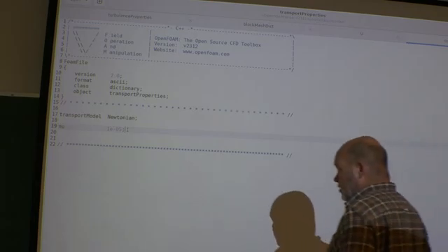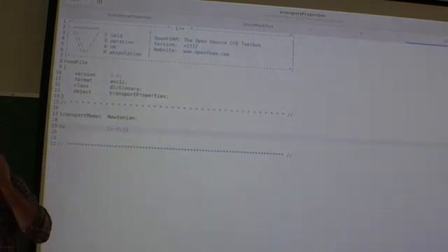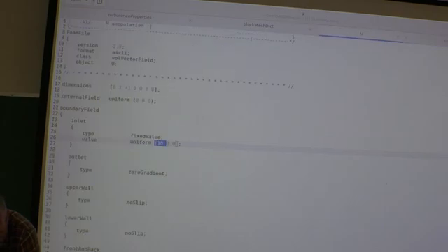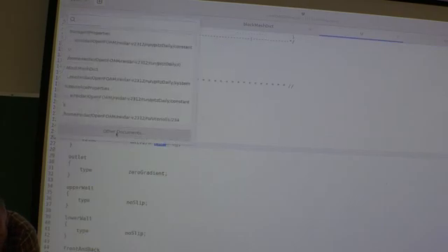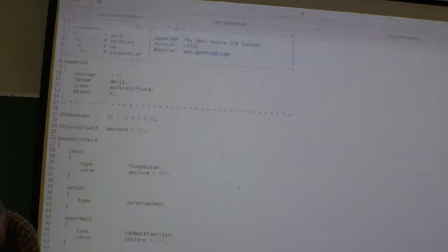So yeah, it's highly turbulent, clearly. If you want to change the Reynolds number, I would suggest you change the viscosity. That's the easy way, instead of having to create new meshes, everything. Okay, then let's have a look at some of these other files here. What about the k?